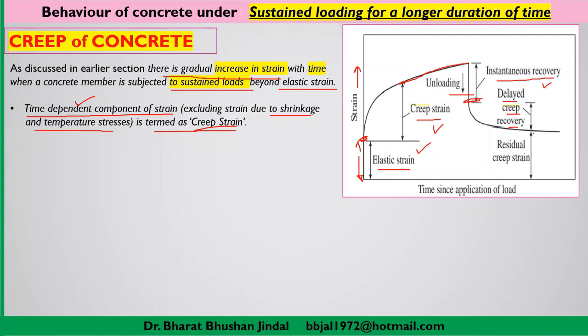After that you observe that the strain remains almost constant, so some creep strain remained within the member, which is termed residual creep strain. From this graph we can easily understand how concrete behaves under sustained loading of longer duration.